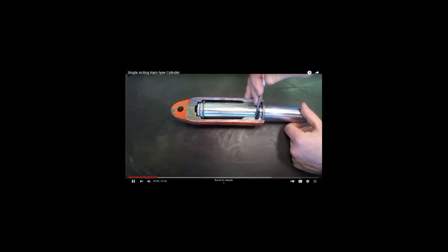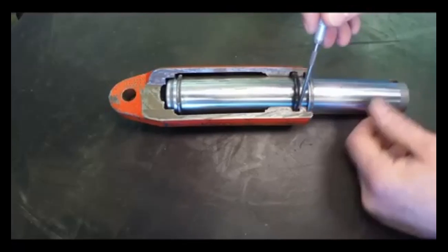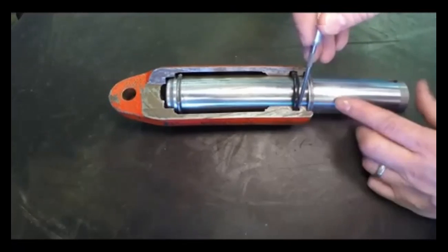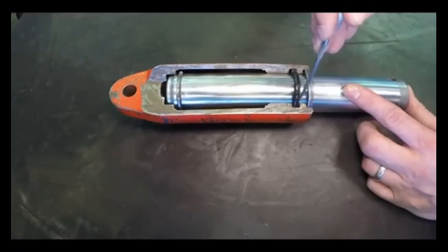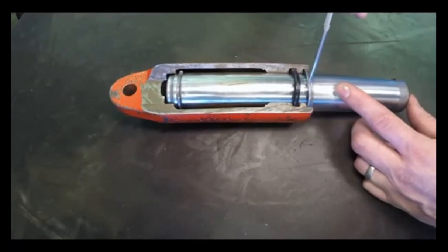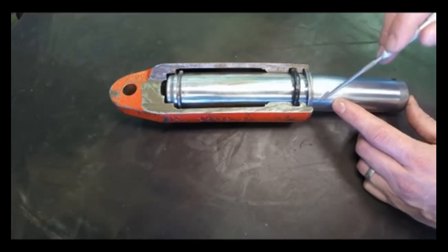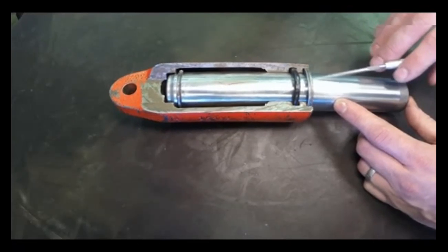O-ring seal, and sometimes you'll see them with an O-ring seal and a plastic backing ring, and that backing ring would be on this side to prevent that O-ring from being pushed past this small groove here. High pressure oil has an amazing way of just slicing apart O-rings. And then we see again another dust type seal to prevent any contamination from getting into the cylinder.